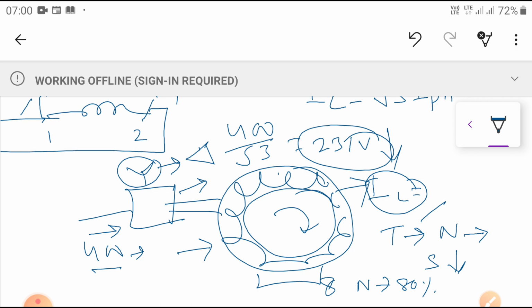That means the six terminals of the winding are taken out into our starter, and the starter initially connects them in star connection. Then the rated voltage given as input to the motor is reduced by root 3 times, and this reduced voltage is given to the winding. The correspondingly reduced current is enough to produce the required torque, which rotates the rotor under normal condition.